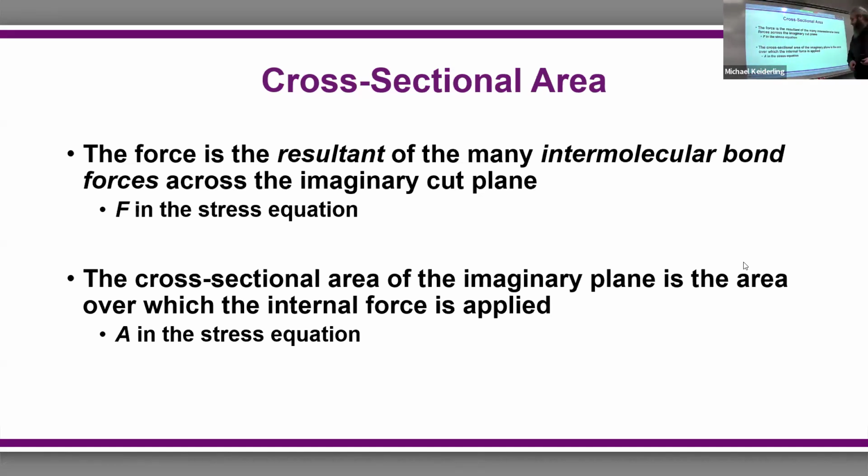So in general, stress is force over cross-sectional area. The unit is newtons per square meter, which is pascals. And often it's going to be a big number because a square meter is a very large area. So a pascal is a very small unit. You'll see lots of megapascals and gigapascals in the book.